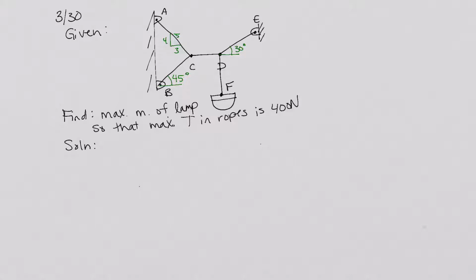I'm not sure where I should start. I'm either at D or C. I'm going to start at D. Yeah, D, because just to tell you my reasoning: at point D we have one vertical force and one horizontal force. So I'll do a free body diagram. But we have this, and then one that's on both axes. So I think that'll be a little more simple versus point C, where there are two that are on diagonals. So that's just a little bit of my reasoning. But this is point D.